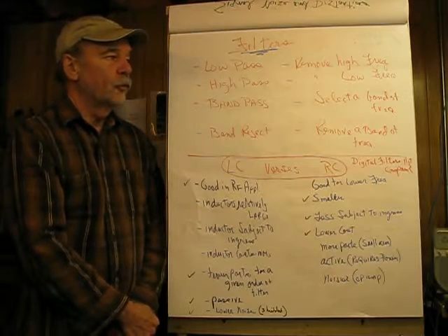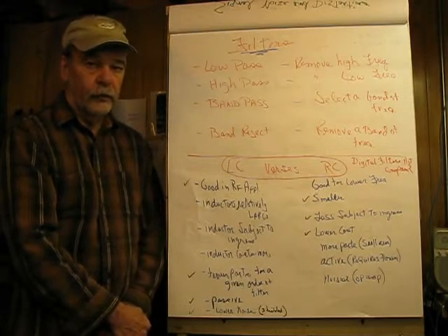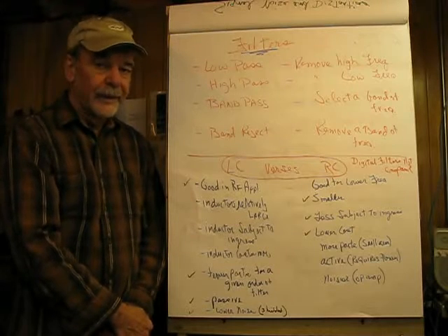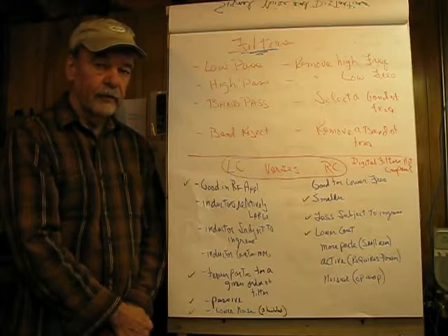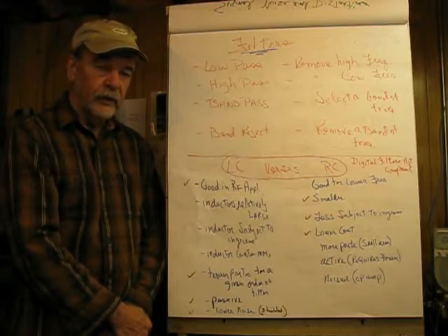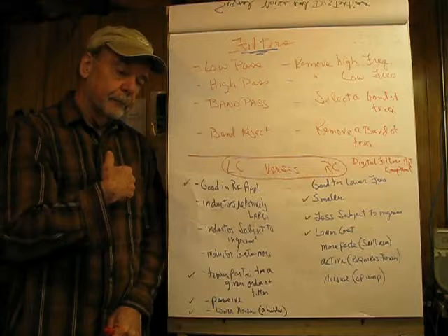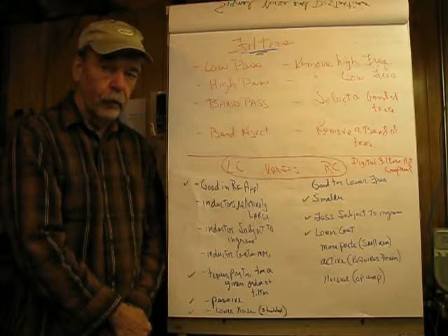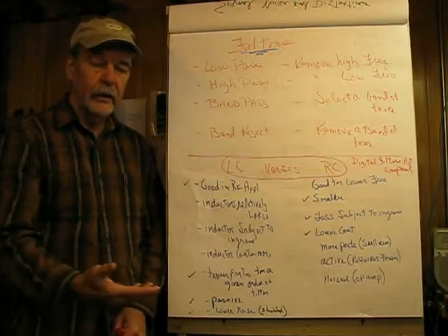Low pass also applies if you're making a signal to noise measurement, say for audio. You don't really need to measure noise content above 15 kilohertz. So if you eliminate that, when you make your actual test, it'll give you a more definitive answer of the true value of the signal to noise ratio that people can actually hear.